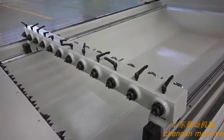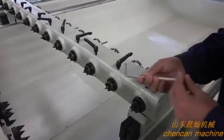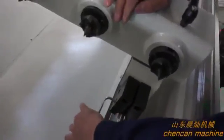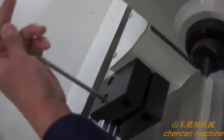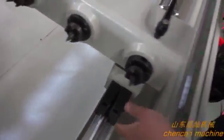Now I show you. We use this tool, the 6 mm Allen key. Here we have the screw. We can loosen it, and then we can move. The same way, when we need to lock, we lock the gear.